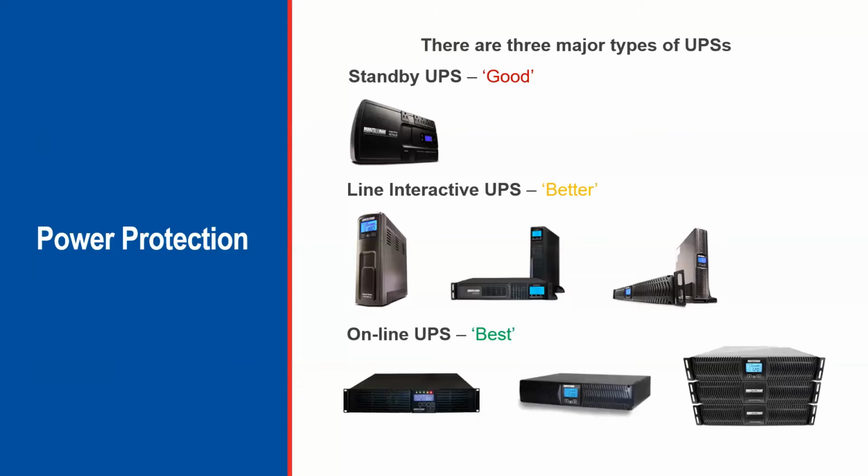As I mentioned, there are three major types of UPSs. These UPSs can really be looked at as a good, better, best arrangement. Standby UPSs, which is the first category that you see there, represents the good solution. Line interactive UPSs being the better solution, and true online UPSs being the best solution available for power protection.